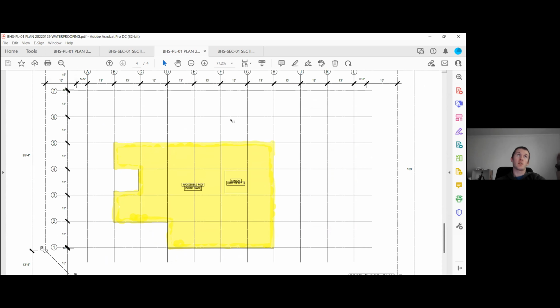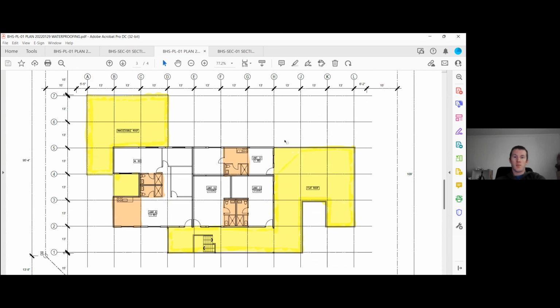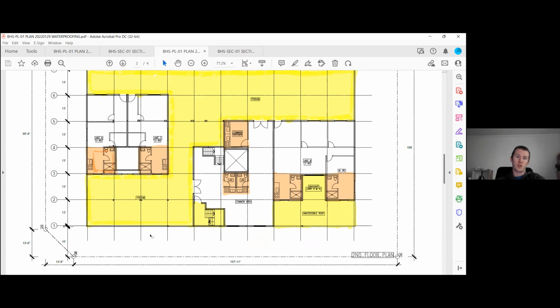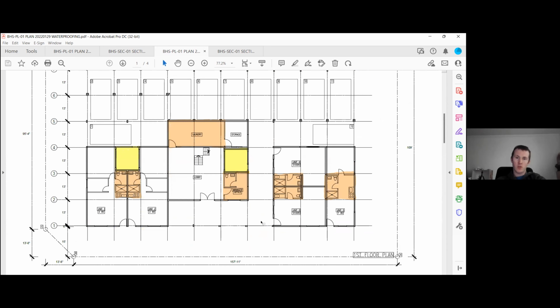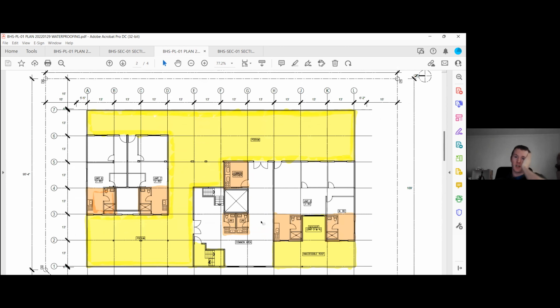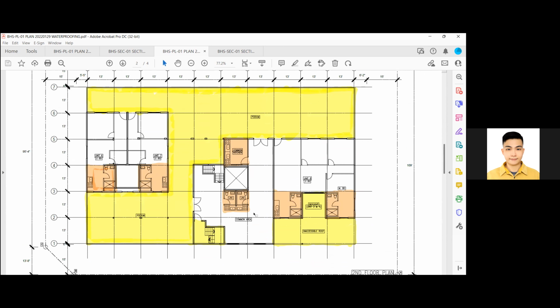One last thing we talked about with Todd was plumbing cores. He advocated using these plumbing walls, which generally run totally vertical through the building, and then all the plumbing and other utilities connect up to these and are able to run vertically. The same goes for the ventilation, they run vertically up them. Generally that's an 18-inch to 2-foot area that's hidden. In this sense, it might make sense to do it behind plumbing areas, or in inaccessible plumbing areas.